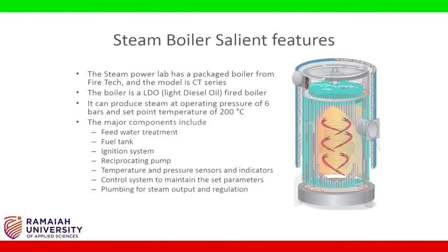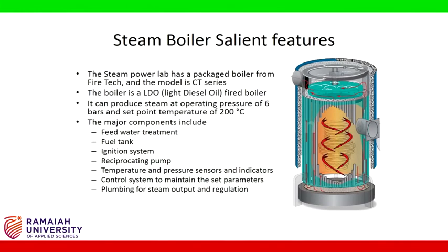The Steam Power Lab has a package boiler from Firetech and the model is CT series. The boiler is a LDO (light diesel oil) fired boiler. It can produce steam at operating pressure of 6 bars and set point temperature of 200 degrees Celsius.